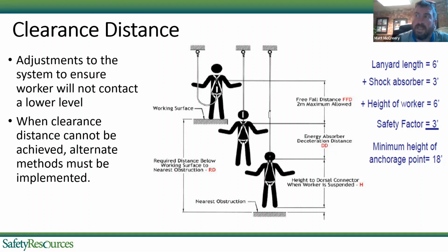They were high enough that fall equipment was required, but low enough that it was very hard to tie off. If I get 3 feet away from my anchor, I'm still hitting the ground. So what we ended up having to do, and I think they bid it right the second time, was set up scaffolding all the way around the roof in order to eliminate the fall completely. That's very unique, very niche, but I wanted to make mention of it.